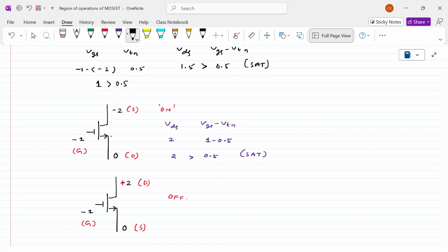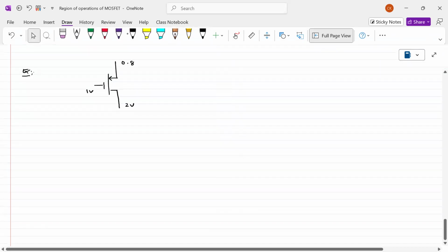First you have to fix which terminal is the source and drain, because source and drain are symmetrical quantities actually, since it is n plus and n plus, there is no difference at all. The difference comes into the picture by applying the potential difference. Then you have to decide which one is the source and which one is the drain. That's the importance of the MOSFETs.